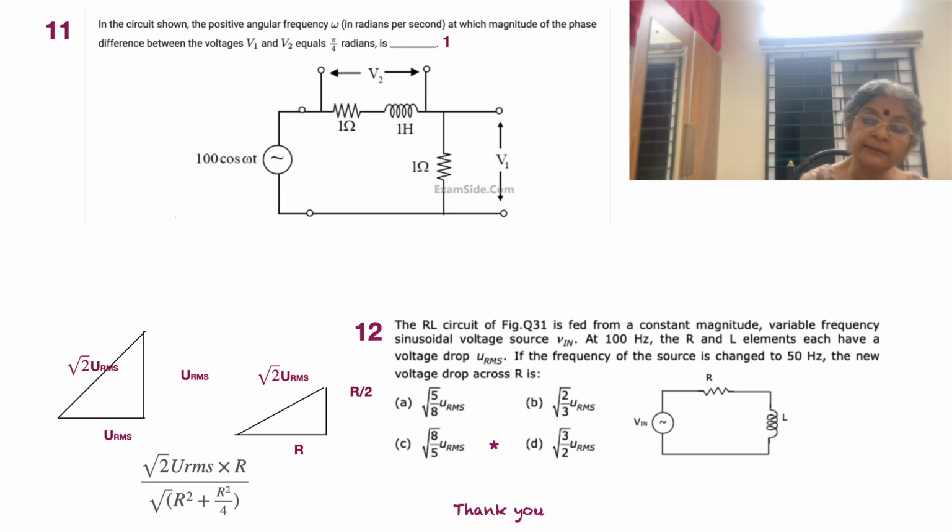At 100 Hertz, the R and L elements each have a voltage drop equal to V RMS. What's special is that these voltage drops are vectors, so you get the total voltage as a vectorial addition of both. It's V RMS squared plus V RMS squared, and the square root gives the total voltage, V in equal to root 2 V RMS. So I suppose that's clear, and a diagram is given to explain this.